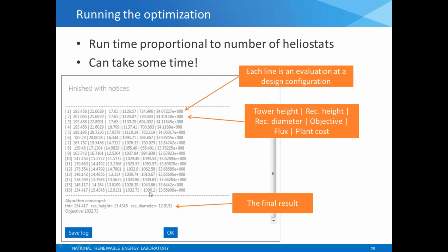The other thing to note is on the flux constraint. This is an approximate constraint, so you might see an optimal solution that's 6 watts per meter squared above your 1,000 limit. If that's a problem, you can go back and push that limit downwards in your inputs. So you might say, well, optimize for 975 instead of 1,000, and typically what you see is it pushes up against this limit and goes a little bit over. So if it's really important that you don't exceed that limit, go back and be a little more conservative in your maximum flux.